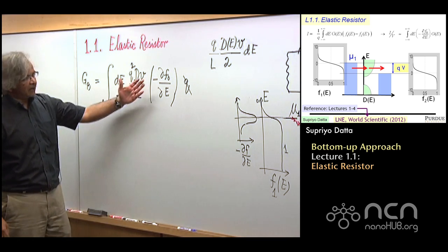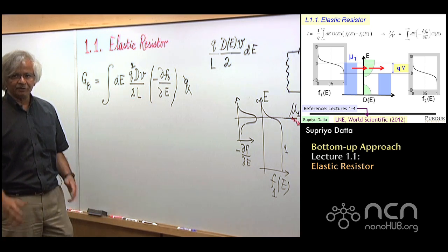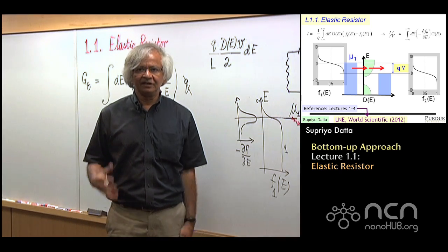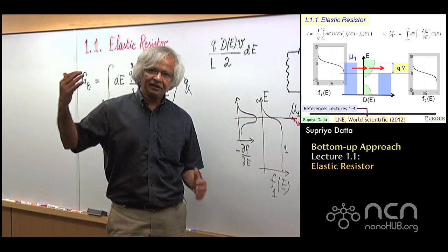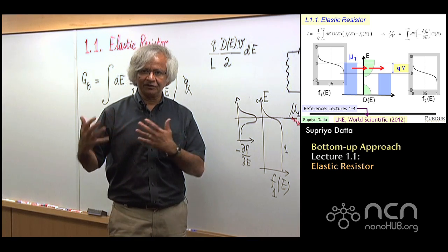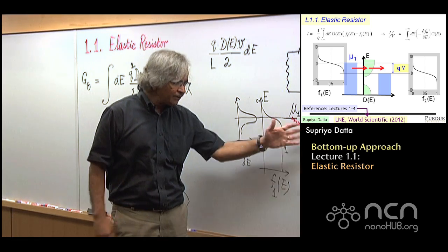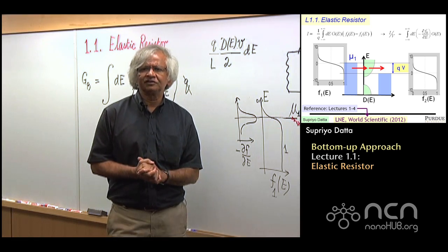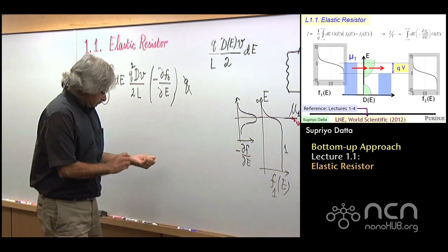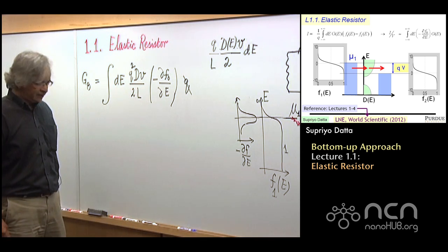Now, so far, this entire discussion has been what you might call semi-classical. It's not fully classical because, of course, I'm assuming some density of states. And usually that density of states contains quantum mechanical input because it might involve effective mass or other knowledge about the energy states. But given the density of states, you're thinking of electrons just semi-classically as particles on a highway. And from that you get this expression Q squared dV over 2L.